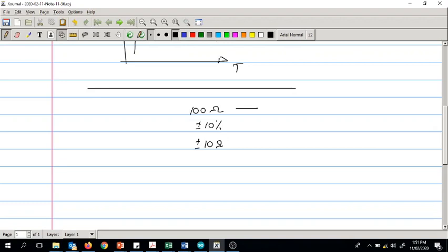So this can be between 110 ohms and 90 ohms. The one below this is 82 ohms, right? In the E12 series, the next lower side value is 82. The higher side value is 120 ohms. So now you can see that these edges do not overlap with the next adjacent values.